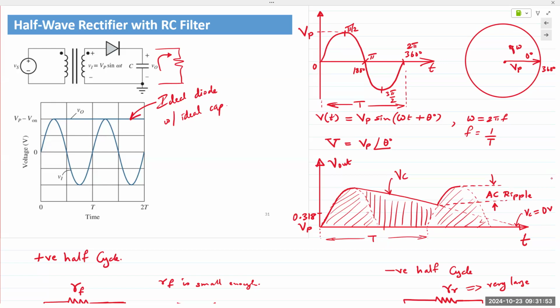And this is jumping a little bit ahead, but in a true power supply, one of the minimum things we would add at the output would be, after the capacitor, we'll feed this into a regulator. The simplest of regulators is a Zener diode. So we would connect a Zener diode after the capacitor or in parallel with the capacitor. The Zener diode holds its output voltage constant for any level of input. Once it turns on, that ripple will also go away. So we obtain a near flat DC line using multiple different components. But as of now, we are just looking at the diode and the capacitor.